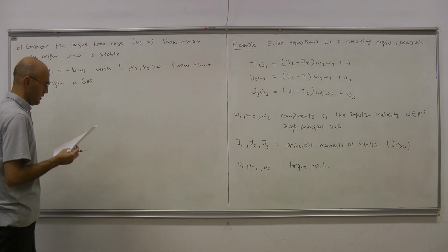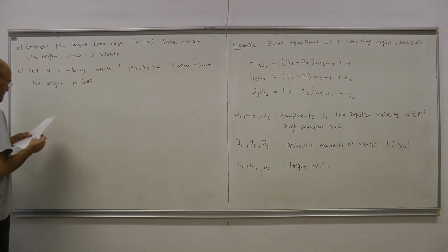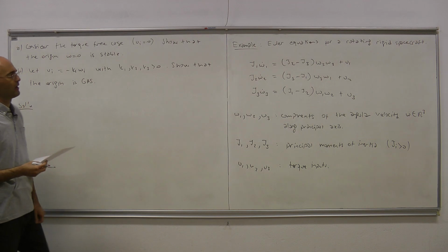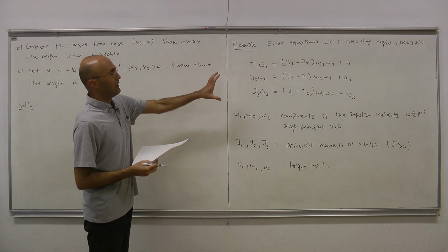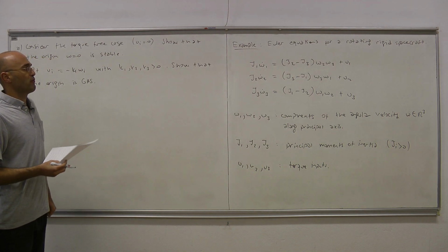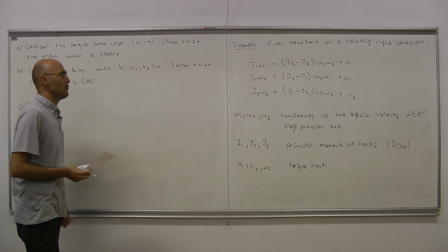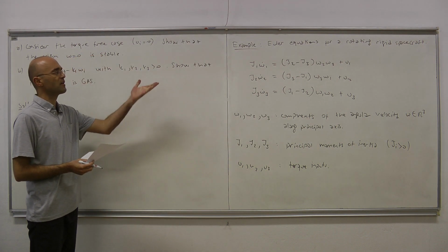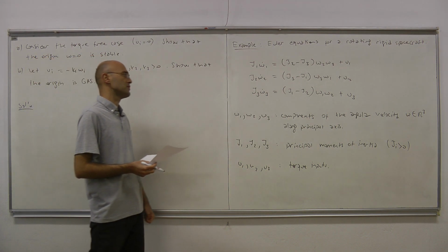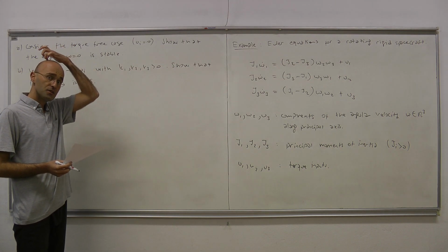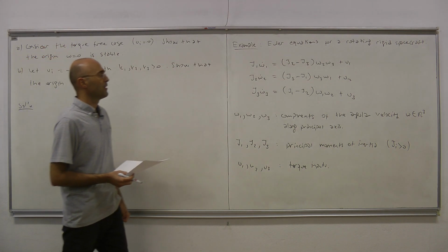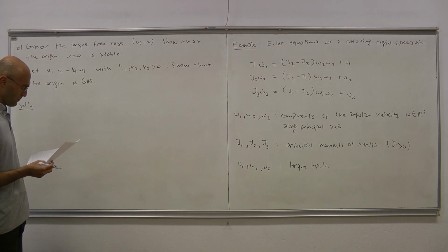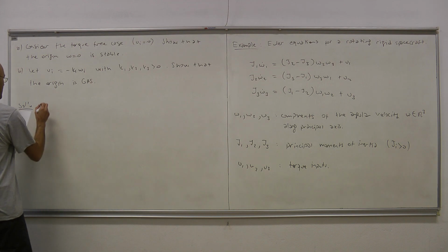Now, let's start dealing with the problem from the point of view of Lyapunov's stability theorem. For that, what we need is a Lyapunov function. This is a physical system, a mechanical system. Therefore, let's go with something that has some physical meaning. For instance, the energy of the system.